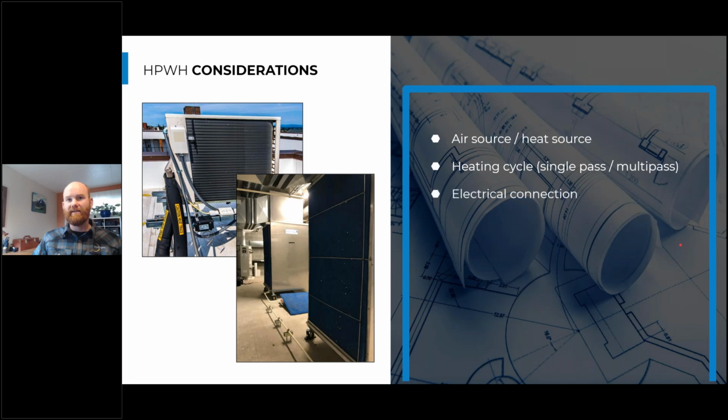We also need to consider our electrical connections. You're typically working on a team when we're working on these buildings, and so we have to work with the electricians and other trades for these systems. And they might be making some assumptions. One of those assumptions, maybe it's a gas water heater, which typically doesn't have much of an electrical connection requirement. It just might be a few 120, 20 amp circuits in the mechanical room.